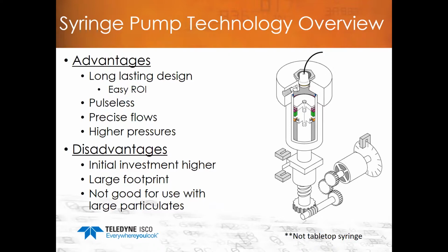You would not want to use large particulates in this case. It could probably handle it, but it might scrape the inside of the cylinder and potentially impact the ability to pump at such a fine rate or precise rate. Also, scratched cylinders will reduce the performance life of the syringe pump technology.